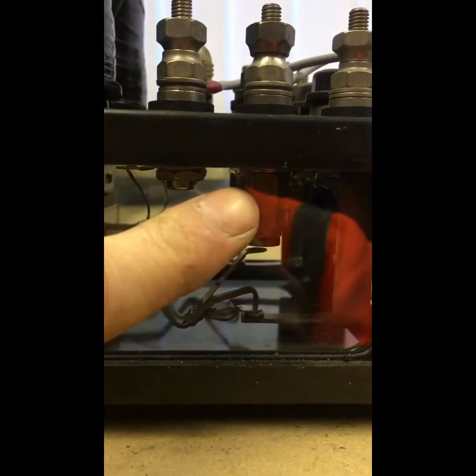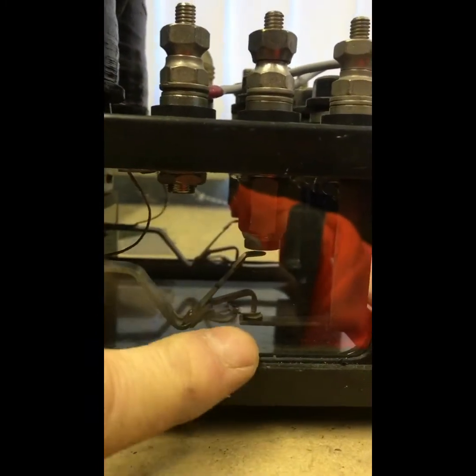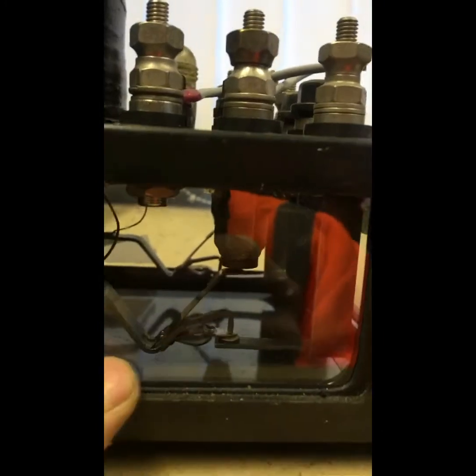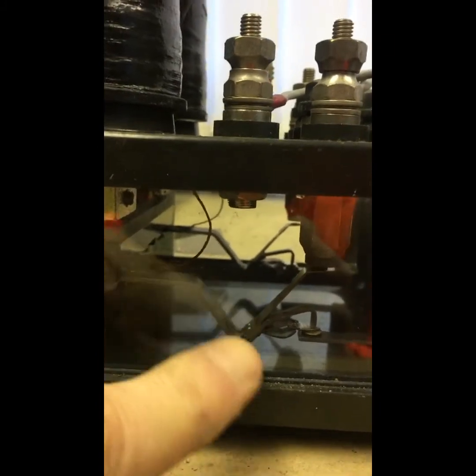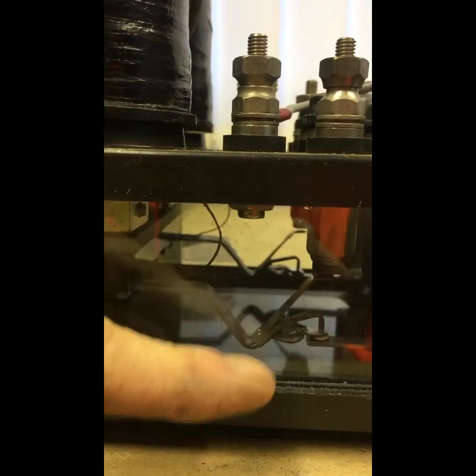And you can appreciate the contact arrangement inside. So here we have our front contact when the track is clear, our back contact when the track is occupied, our armature, and also we have this thin braided copper band which carries a current through because obviously the armature is moving, picking and dropping, picking and dropping.